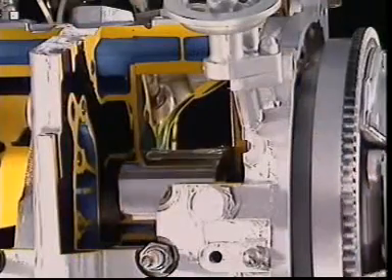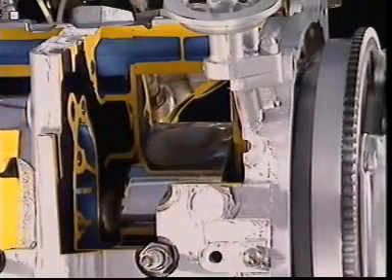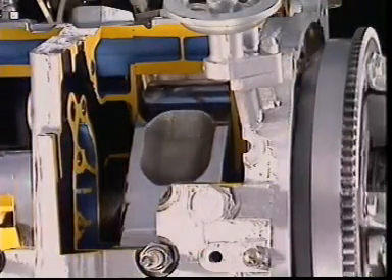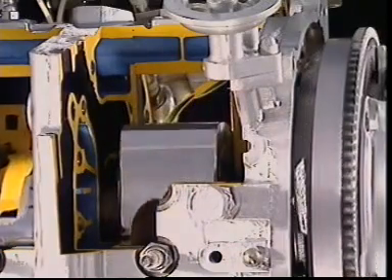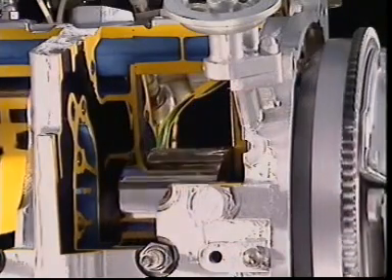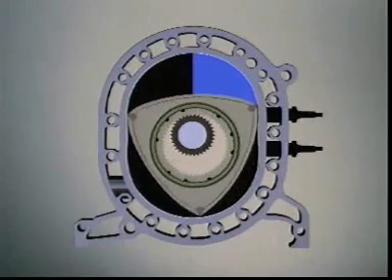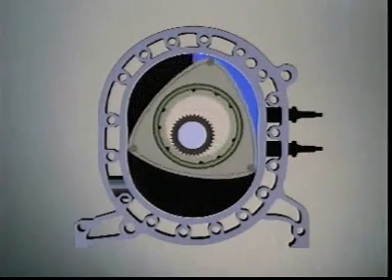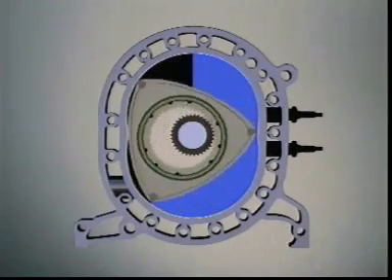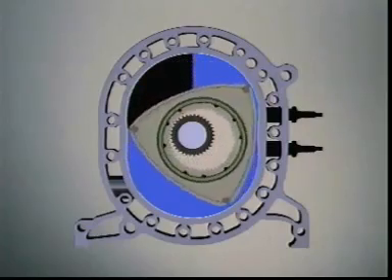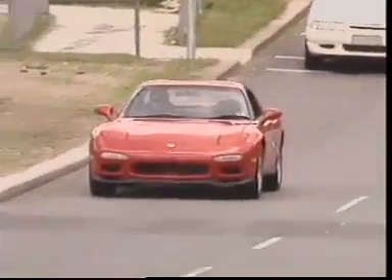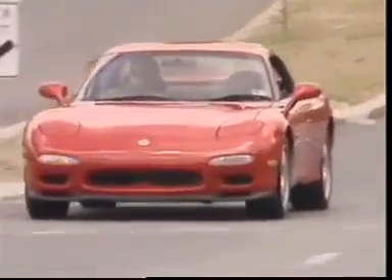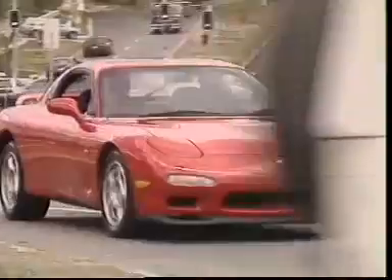A rotary engine has a rotor, not a piston, and it's called rotary because the rotor has a planetary motion. It does not reciprocate. The rotor is roughly triangular in shape, and it turns inside a housing which is a particular geometric shape called an epitrochoid curve. Because it spins rather than moves up and down, engine operation is said to be very smooth and vibration-free.